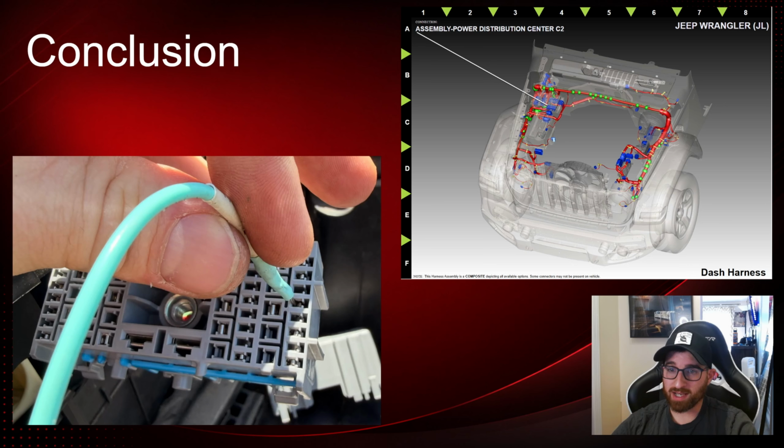I'm not sure why we had a loose terminal tension, especially on a 2021 Jeep Wrangler. It's a newer car. I can't imagine that anybody has had this apart or been in here. So I was a little confused as to why it was spread. So we ended up tightening this up. It seemed like it was going to be good. If any issues return, we are going to have to get a new terminal for this one, but it did tighten up. It didn't seem like anything was broken, maybe just from heat on the circuit or something like that.